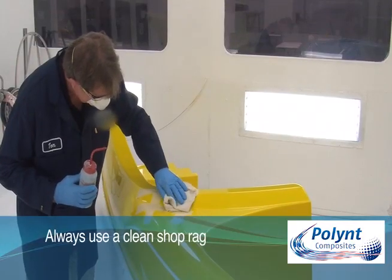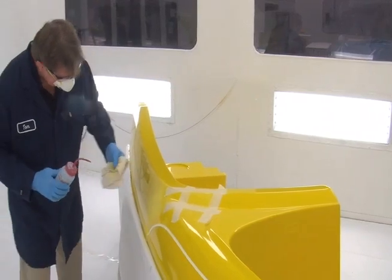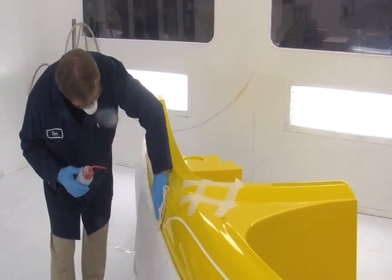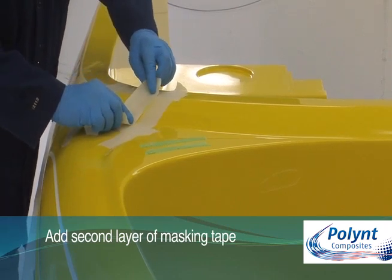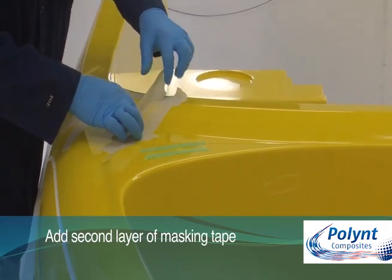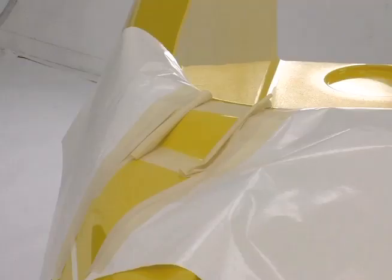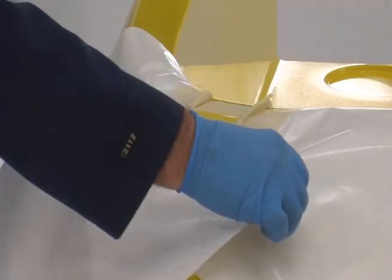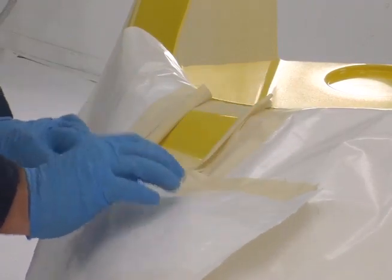Always use a clean cloth to remove the sanding dust, oils, wax and other contaminants, especially when changing to a different sandpaper grit. Place a second layer of tape about 3 to 5 mm inside the sanded edge boundary. Cover the surrounding areas to protect them from overspray. Keep the repair area as small as possible.